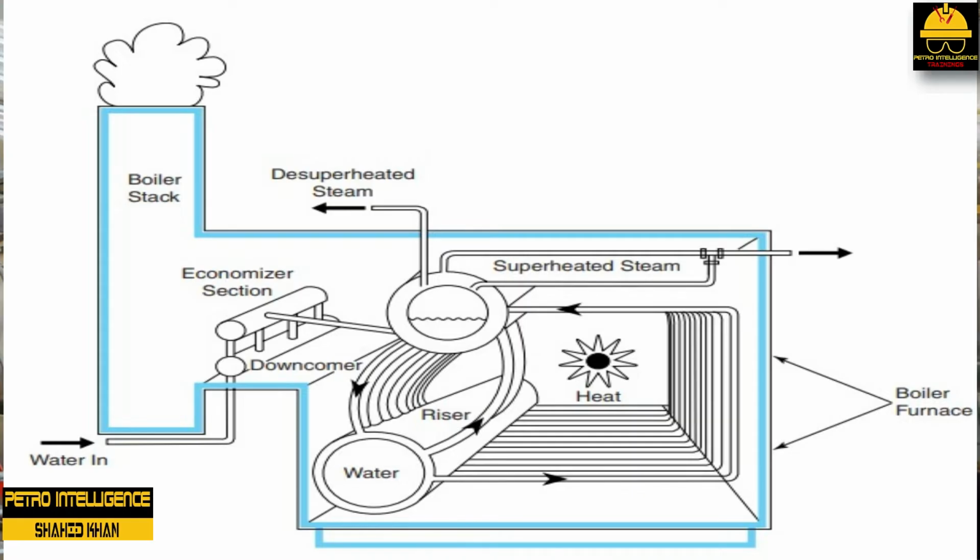exit the boiler. As heat is applied to the boiler firebox, water flows from the upper drum through downcomers into the lower drum. Tubes, called risers, cause water and steam to flow into the upper drum because of density differences. Boiler water circulation operates under the principle of differential density.